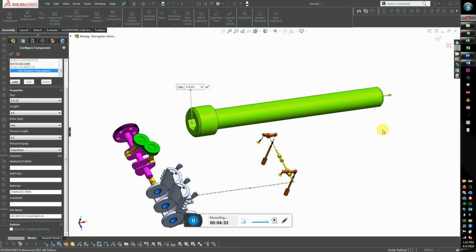So for our DLAs and final projects, instead of going to McMaster trying to pull some bolt through, just figure out what size and everything it is, use the Toolbox wizard, and then just take the part number and put it in the BOM. Oh, okay. Yep. That'll make life easier.